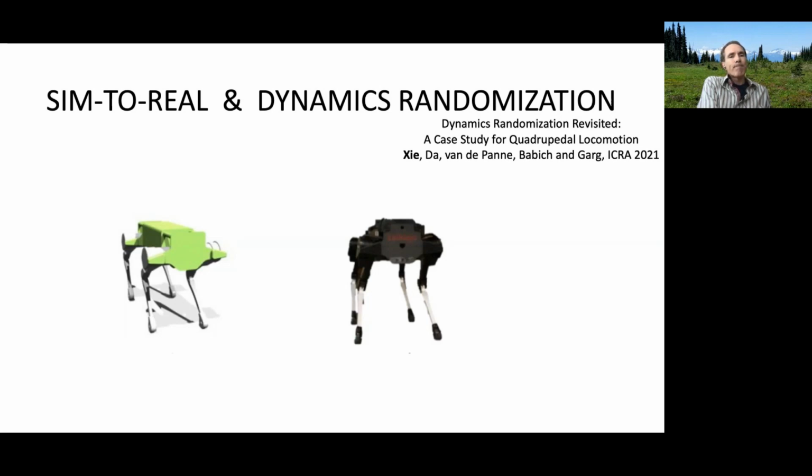If you randomize with respect to body mass, hoping that helps, but the real problem is latency in your feedback, then you're hoping to tackle that by randomizing the mass and some joint frictions, well then maybe that's not helpful, right? Of course that assumes that you have some way of discovering where the real mismatches are, and there's no formulaic answer for that.